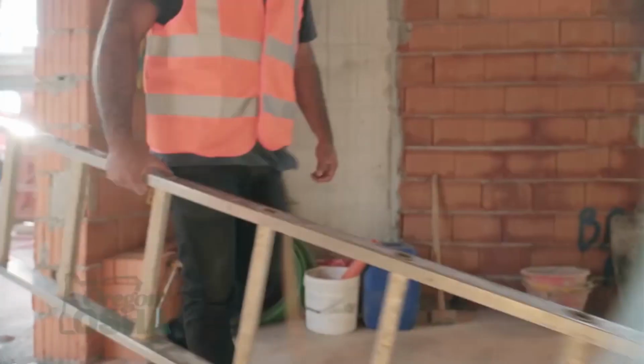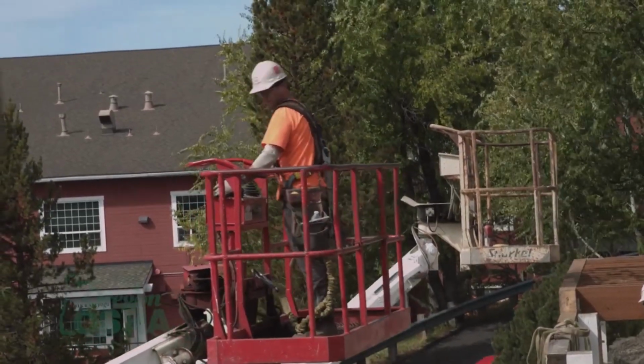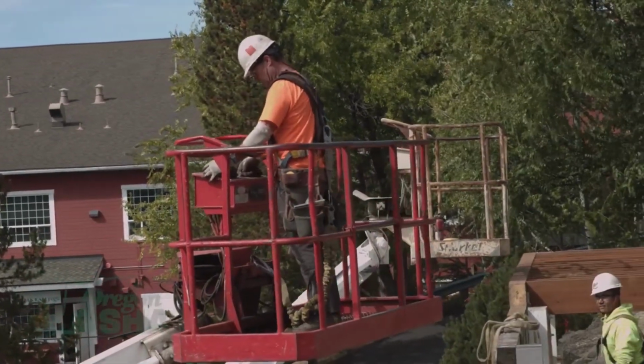So with fall protection, you have to have a rescue plan. Our company does have a rescue plan. First and foremost, if somebody falls off the roof, somebody's calling 911. The crew then works to get a ladder, to get a lift, whatever we need to do to get over to the person that has fallen, to be able to help them get picked up and get that pressure off their body, so then we can get them disconnected and get them down to the ground, and medical personnel can check them out and make sure they're okay.